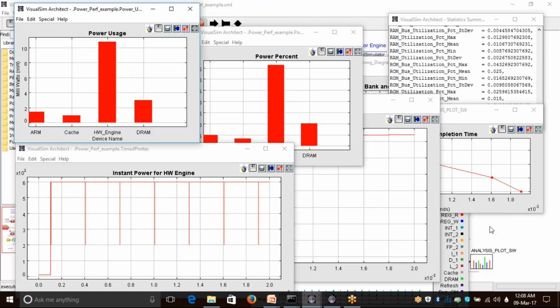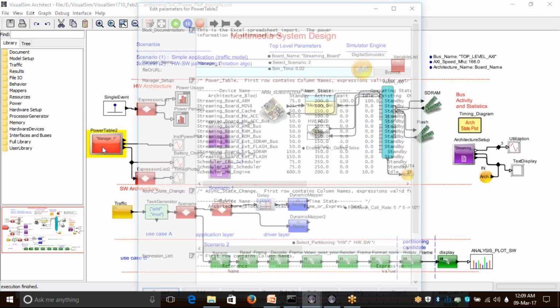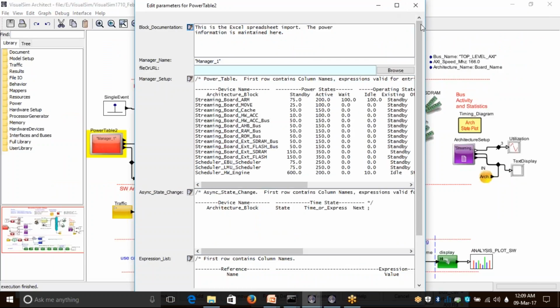So what I'm going to do at this point is shut down the hardware engine if I'm not running any tasks for a period of time. For example, I'll wait for 1 nanosecond or 1 microsecond, and if I don't receive any task request, I'll shut down to a standby state or deep sleep mode. Okay, so I'm going to add that particular line here.